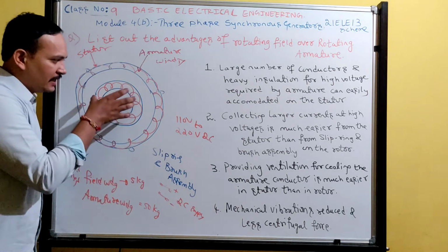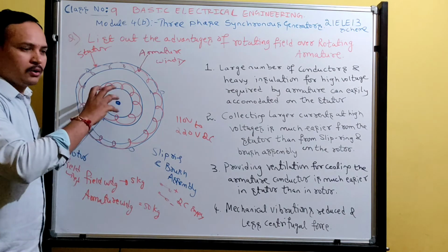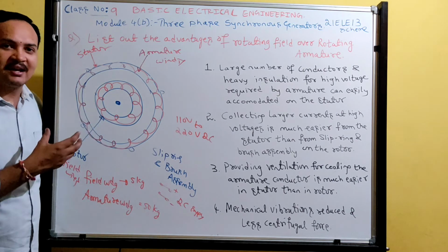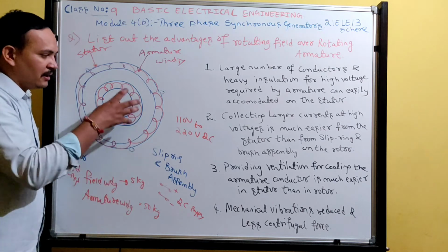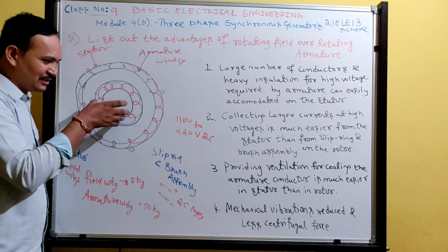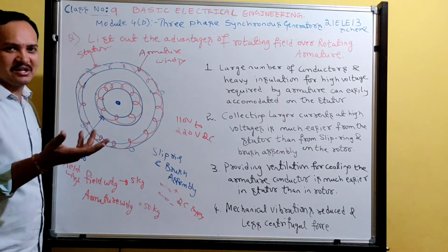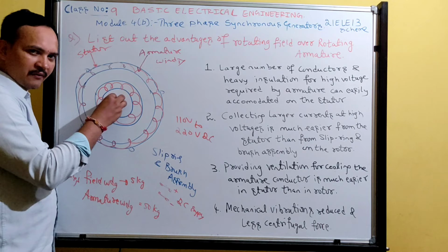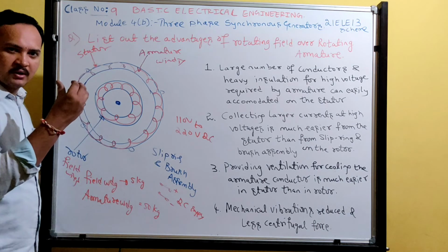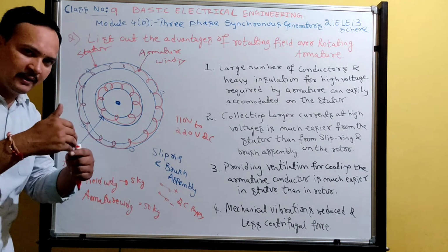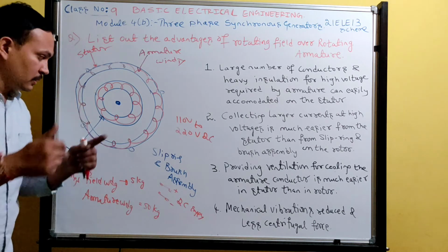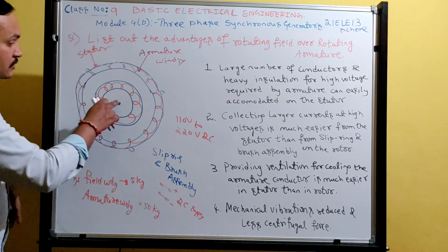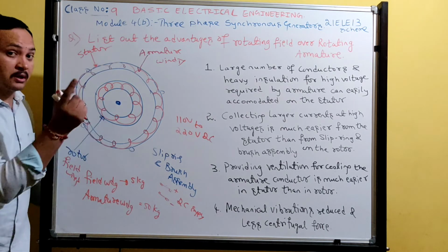If I rotate the field, the net inertia to move the rotor is less, and it moves smoothly. If inertia is higher, say if I put armature winding in the rotor, the total weight increases, and inertia also increases. It may refuse to rotate. Even though this shaft is coupled to the turbine shaft, water falls and the turbine runs smoothly. The turbine shaft is coupled to the rotor shaft of the alternator.